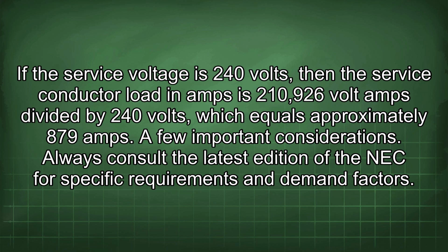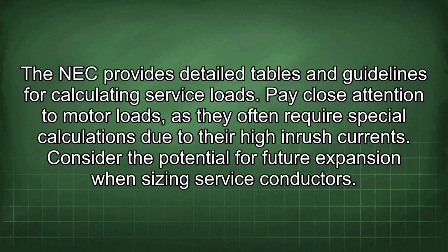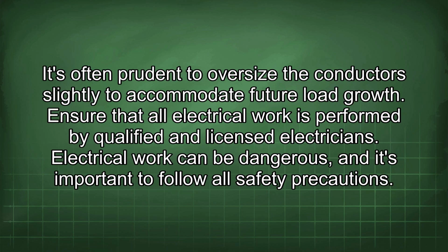A few important considerations. Always consult the latest edition of the NEC for specific requirements and demand factors. The NEC provides detailed tables and guidelines for calculating service loads. Pay close attention to motor loads, as they often require special calculations due to their high inrush currents. Consider the potential for future expansion when sizing service conductors. It's often prudent to oversize the conductors slightly to accommodate future load growth.